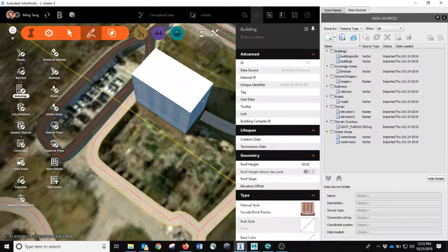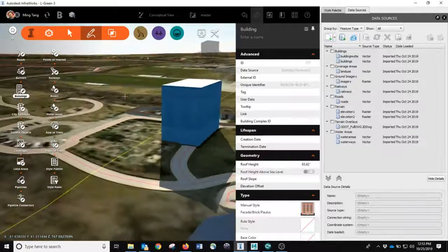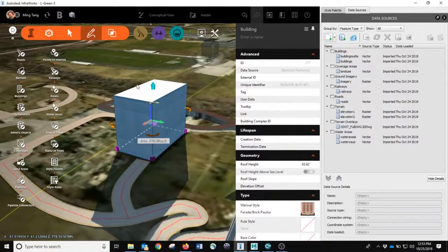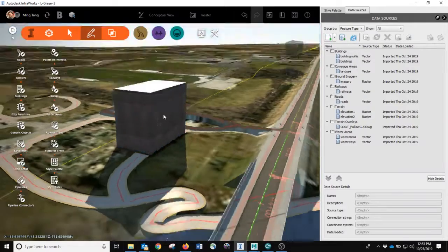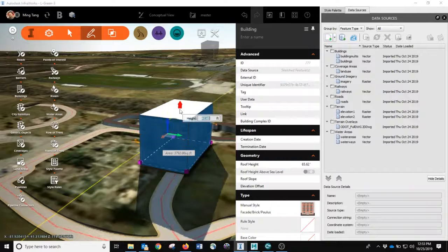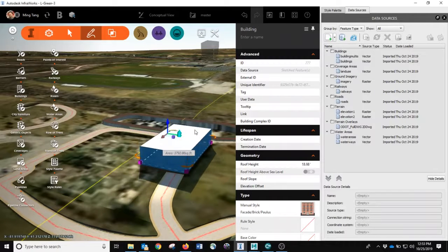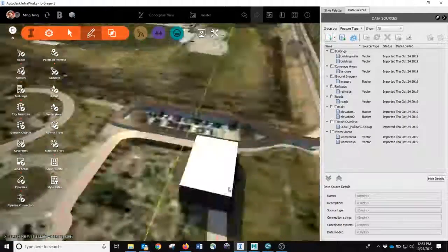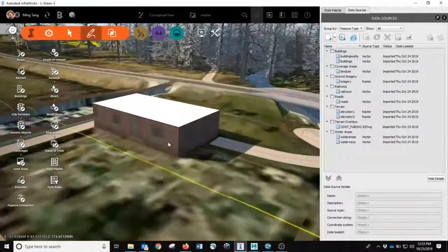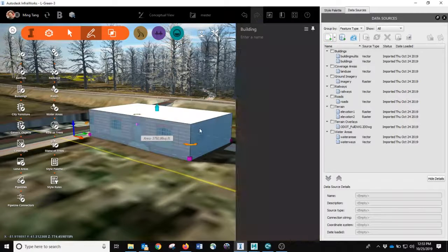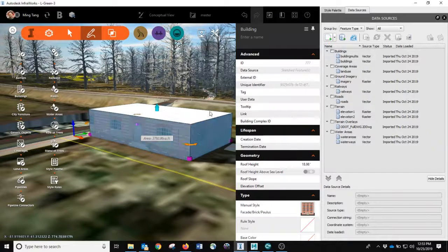You're done. And you can see the building, of course, is not at the right height. However, this one is a procedural model. That means if I select the building and push it down close to 1 story high, you see the facade will automatically update. So you don't really see the 4 stories anymore. So that's a really quick way to generate a rough building.